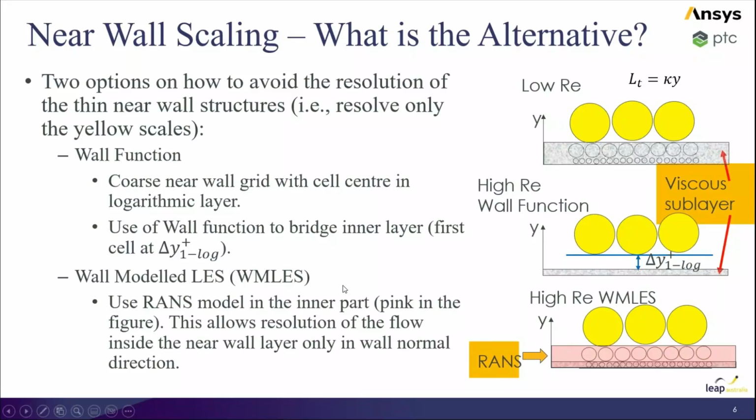So the other option is to do modeling in here. We know from all the derivation of the RANS models that where they're really good is in the boundary layer, especially the SST model, which has been tuned for that. So SST is going to do a really good job. If it comes to an adverse pressure gradient, it's going to want to separate, and it's been tuned to do that, where the log law will just carry on sticking the flow to the wall. So we can see there's a big advantage, if we could, of using an appropriate model in the two different domains.